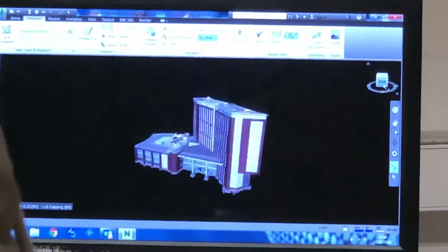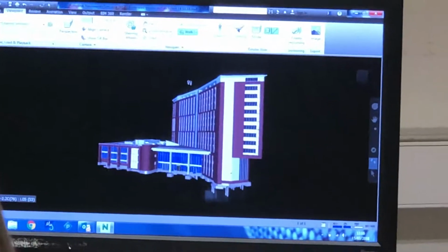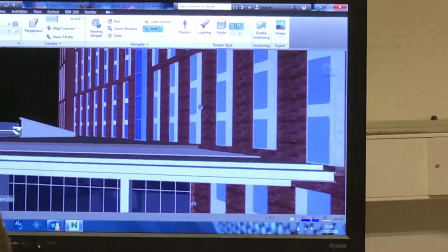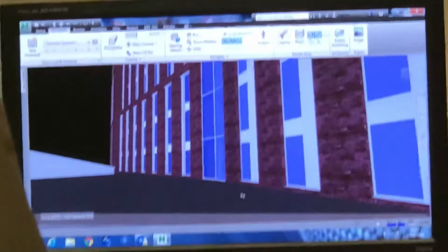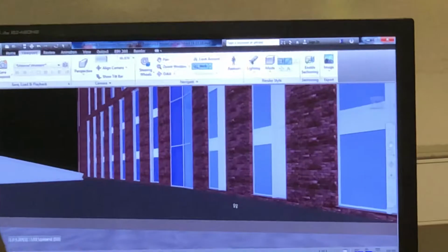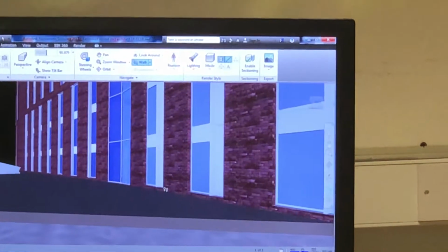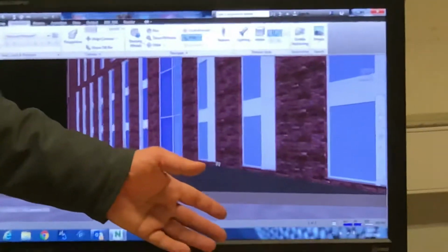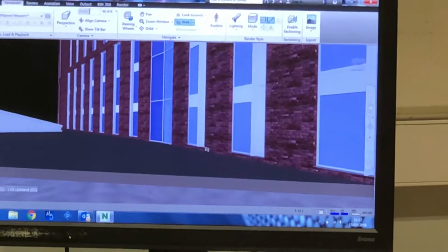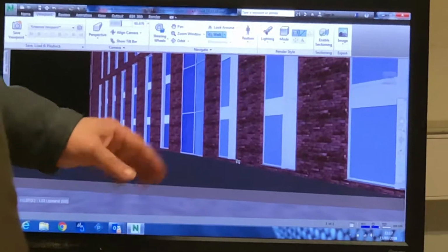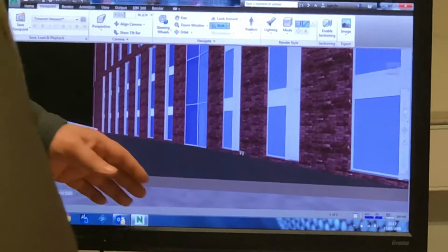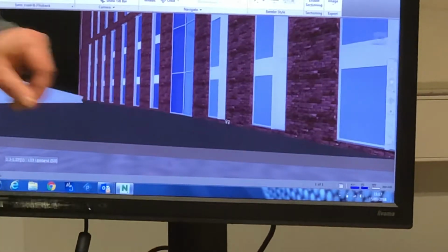With regards to BIM and clash detection and various things like that, from a construction viewpoint, the way we use it, we go into places like this, which you wouldn't necessarily be able to do with traditional paper drawings because you need a few of them. I can look and see, well, I've got brickwork there, I've got a roof going in there, there's going to be a detail that needs to be developed, or if it's already been developed, I'll need to review it just to see, from a construction viewpoint, whether I put that roof on first, or I build all the way up with the envelope. From a program and buildability viewpoint, I'd like to put the roof on first, because that allows me to work below it. I might not be able to, I've not looked at it yet, but it's things like that.